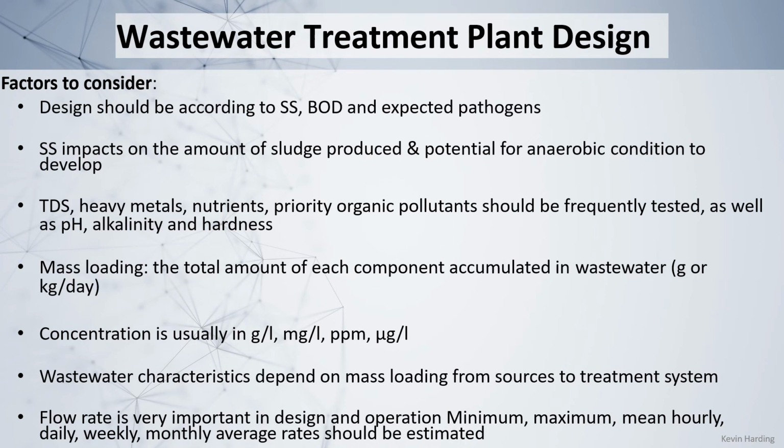So what we're going to look at next week is wastewater treatment plant design, or some more aspects of water, but some things to consider from what we've seen today. When we want to design a wastewater treatment plant, we want to look at how we want to include the suspended solids, SS, as well as the biological oxygen demand, and how we are going to deal with the expected pathogens. So it's 3 different things that we have to look at.